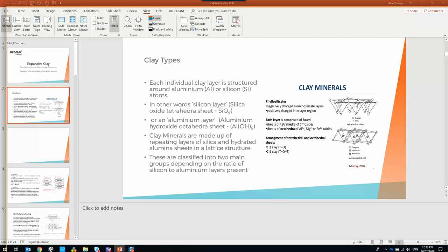So the first option is to get the whole thing so it doesn't touch the ground, so it's fully elevated off the ground, either timber or Bondeck. We've used that quite a bit for residential and commercial, like McLean's grading floor is all fully suspended off the ground. It's also handy, we use it in Dalby, you can let flood water pass under the building as well. And I'll show you, I'll go to the next page first.